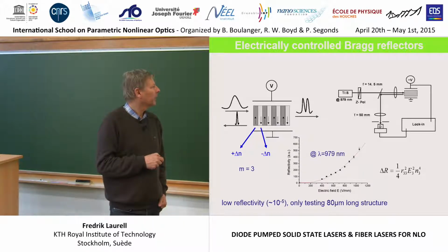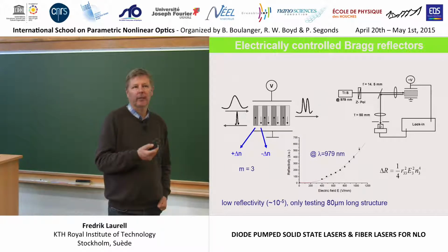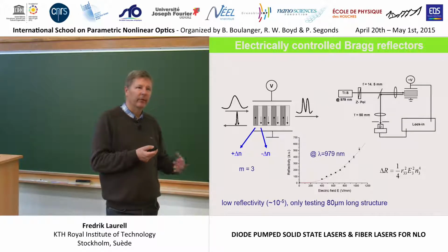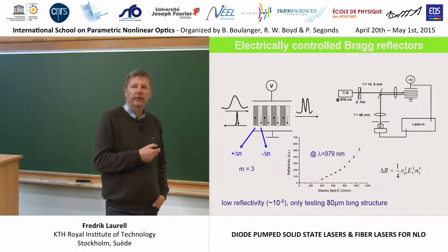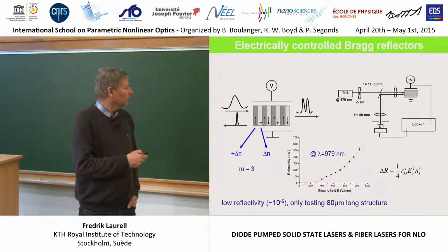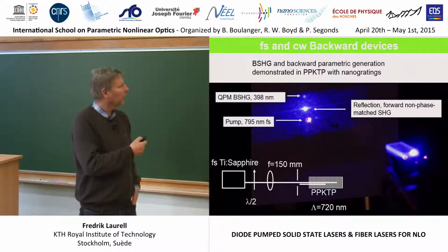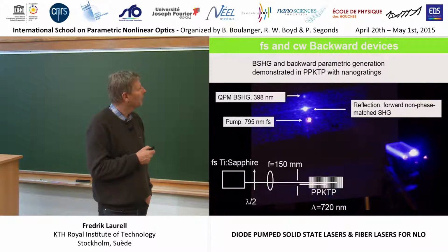And if you do it in a waveguide configuration, it can be quite a low field required to do this. And then it could be interesting, for example, in a telecommunications WDM system if you want to tap off a signal, because this is an electro-optic effect, so it's more or less instantaneous. So you can think of applications here, other applications in telecom.